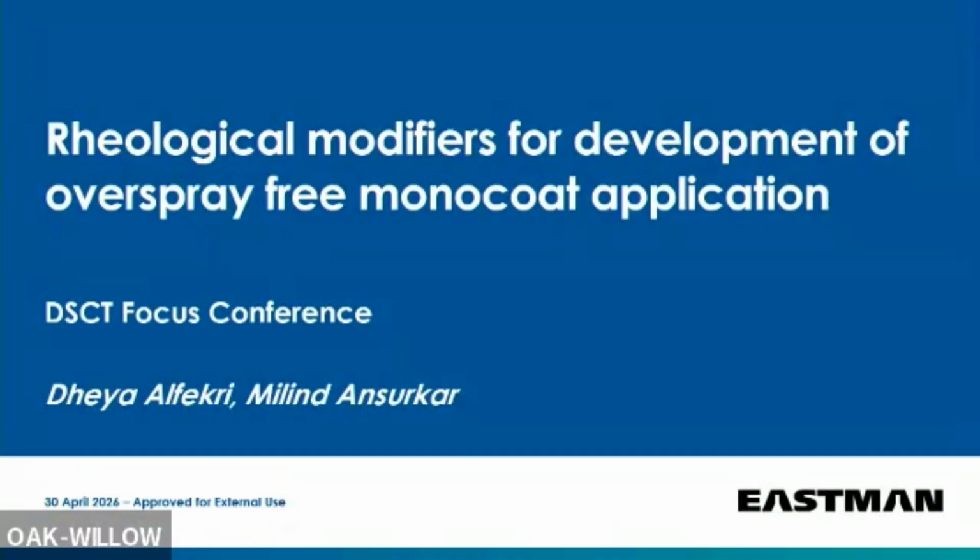So the moment you say digital printing, car body, thick paint, sag control agents or the sag control resins or the additives become very obvious, because you need that sag control over here. And people use that. But what is not very obvious is the rheology modifiers. And hopefully after this presentation, you'll realize that even the rheology modifiers have a role to play over here. And there is a synergy between them and the sag control agents. And hopefully by the end of this, you'll realize how to use them effectively in your overspray applications.